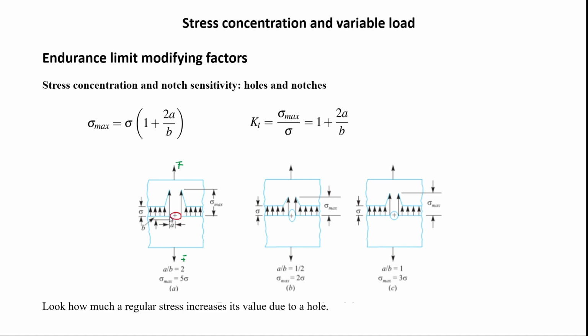Definitely in the vicinity of this ellipse, stresses are going to increase to a certain level. Increases are going to disappear because there's nothing here, and then it appears again, and then goes to the normal level. However, depending on the shape and orientation of that ellipse, you're going to have larger or smaller increases in stresses. And if you have a completely round hole here, then it's also going to be at a certain level.